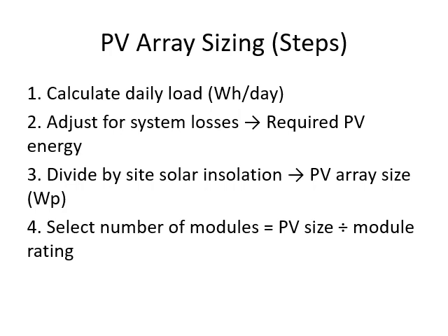Now, let us start with the photovoltaic array sizing. So what are the steps? How do we follow? We are going to see it through a worked out example that I have extracted from ChatGPT for a lump sum value of the daily average requirement. So calculate the daily load, watt hour per day or kilowatt hour per day, then adjust for the system losses. So we will need something called performance ratio for different system, depending on whether it's standalone or it is grid connected, that performance ratio will also change.